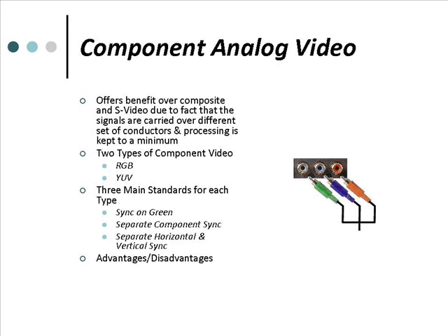Delay in each one of the signal paths must be identical to all the others. If one cable is longer or shorter than the others, then the objects can display ghosts or color fringes on the screen.